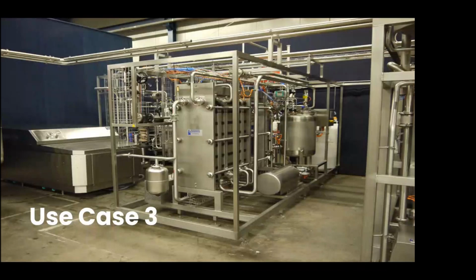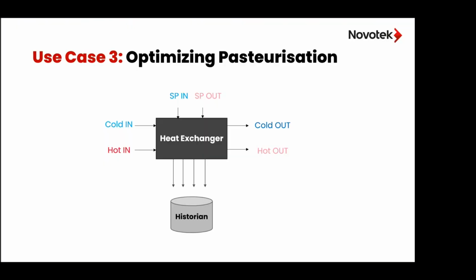This use case is situated at a pasteurizer machine. And of course, we simplified it a bit, but the principle is the same: pasteurization is concentrated at a heat exchanger where two fluids interact with each other, transferring the heat. So we monitor the temperature of the cold and the hot fluids going in, and the temperature of both fluids coming out. And with the set points, we set the desirable output temperature. All the signals are being logged into a historian. And once again, Cameron will demonstrate the advantage of a multivariable controller versus a standard PID controller.